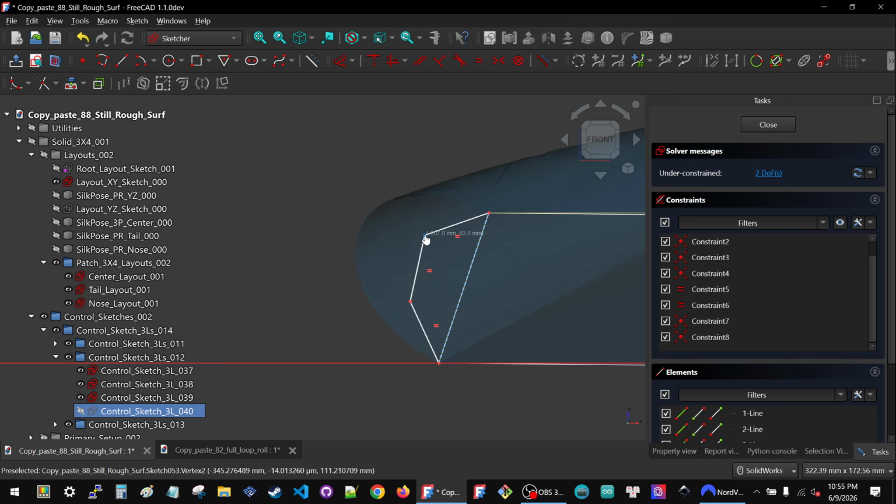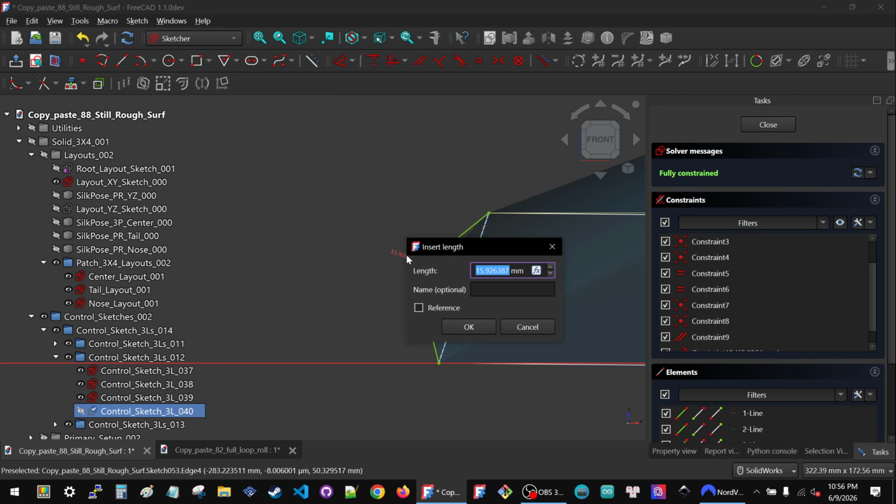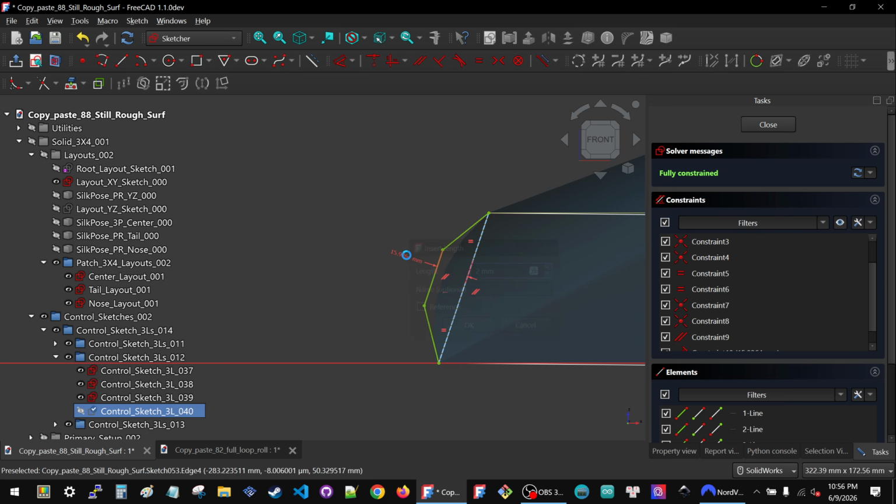It's just that the way the sketcher does the preview when you drag things live has to create additional constraints internally. And sometimes those additional constraints it creates internally, just to be able to handle what you're doing on the screen, lock the sketch, even though there's no valid reason for the sketch to be locked based on the constraints you have. See, I've put in my parallel constraint, but it's not trying to do what it was before, and now I have freedom. So thank you, FreeCAD, for giving us a cool sketch system, even though it's not perfect all the time. Thank you, thank you, thank you.